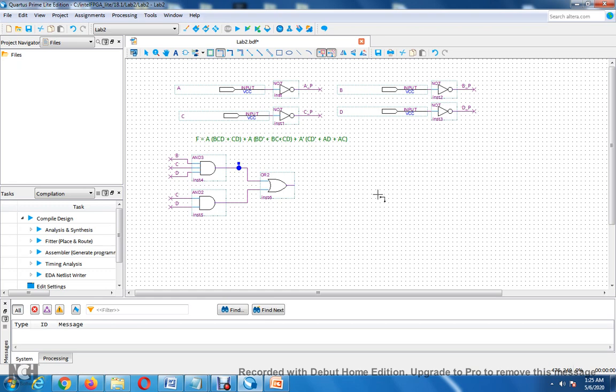Where two wires meet, you don't have that. A junction happens when 3 or more wires meet. Somehow, by drawing with an unsteady hand, they get this kind of tumor where there's no need for a junction because you don't have 3 or more wires meeting. If that happens to you, you have to remove it and redraw it.